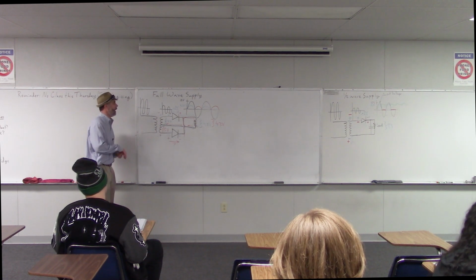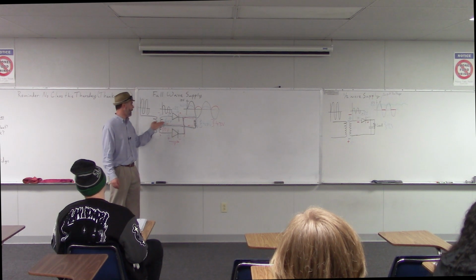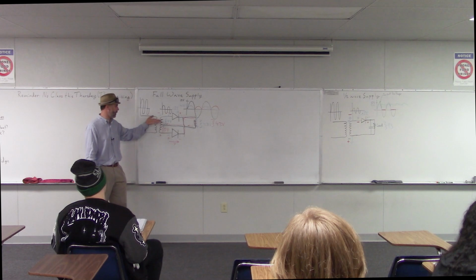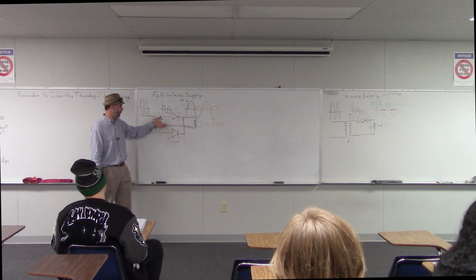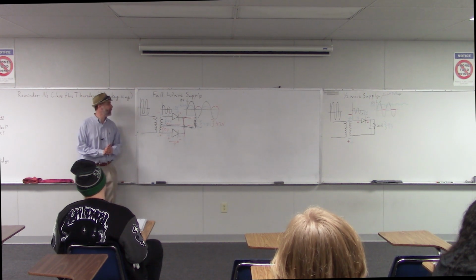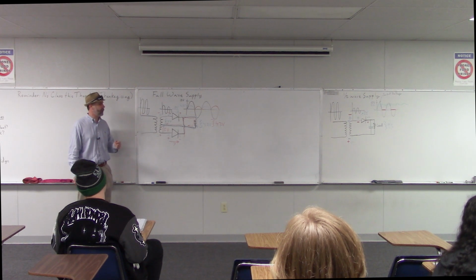Unfortunately, the output voltage is considerably lower than the input because we're using this center tap transformer, and so we're only getting about half of the voltage coming out that we would normally get. So any questions about how that works?